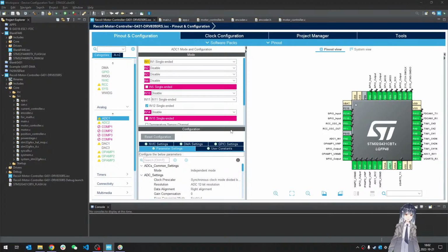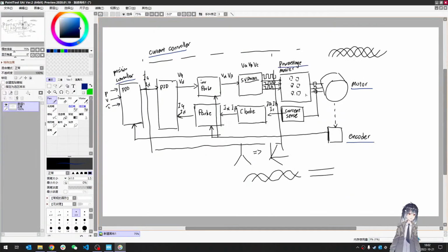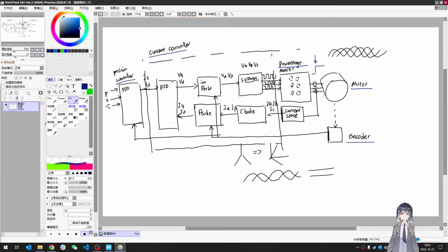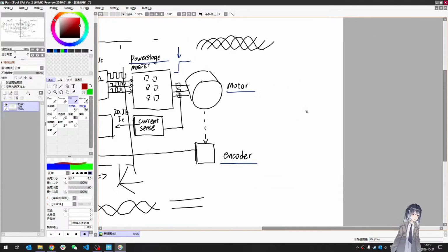As I've mentioned, we have 3 channels of ADC input that sample the phase current, and the sampling needs to happen at a fixed time instant. Okay, this is getting complicated. For 3-phase inverters, the schematic of the inverter is like this.